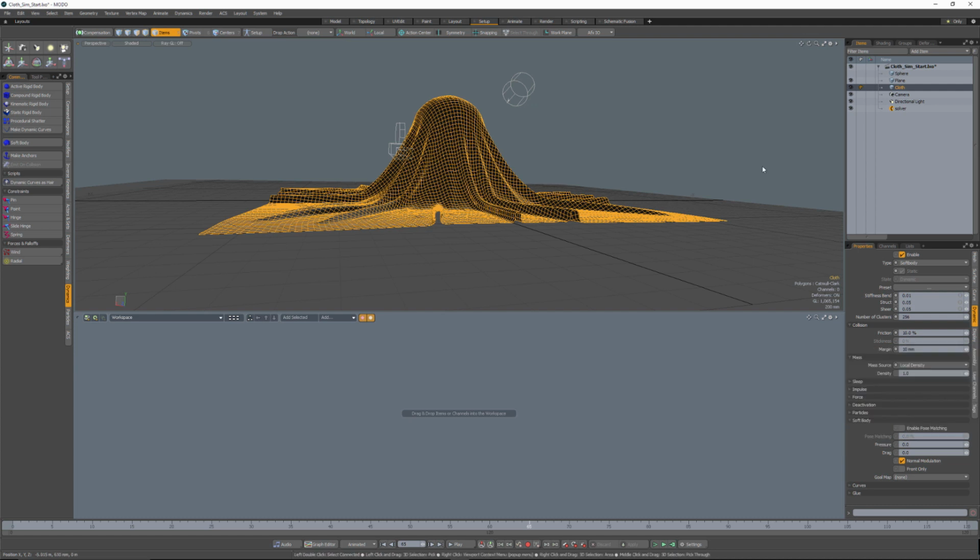It's worth playing with. Remember, start with your resolution low to minimize your frustration. Reduce the number of crashes. As I'm running through this, I should note, Modo didn't crash at all on me. It hung up that one time as we were running the higher resolution cloth sim, but it didn't crash on me. And a part of that is approaching this in a way that's going to be, start with the overall general idea, low resolution, get the look that you're going for, get the overall feel.